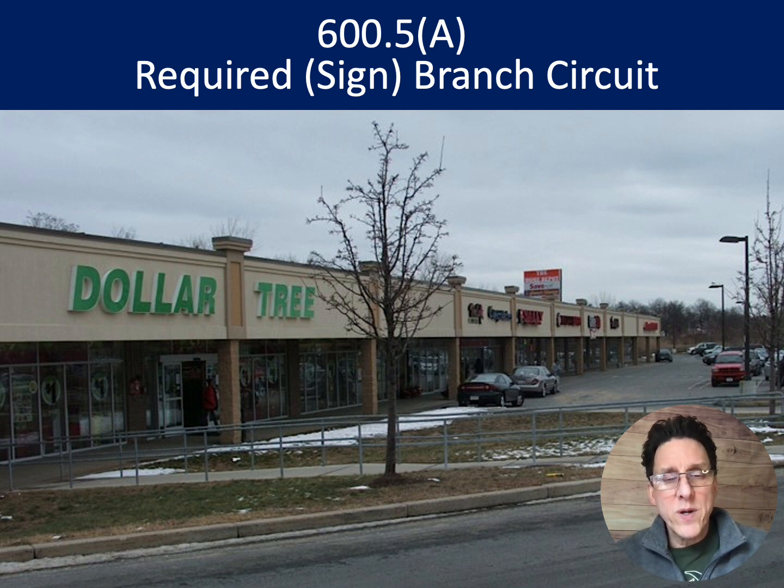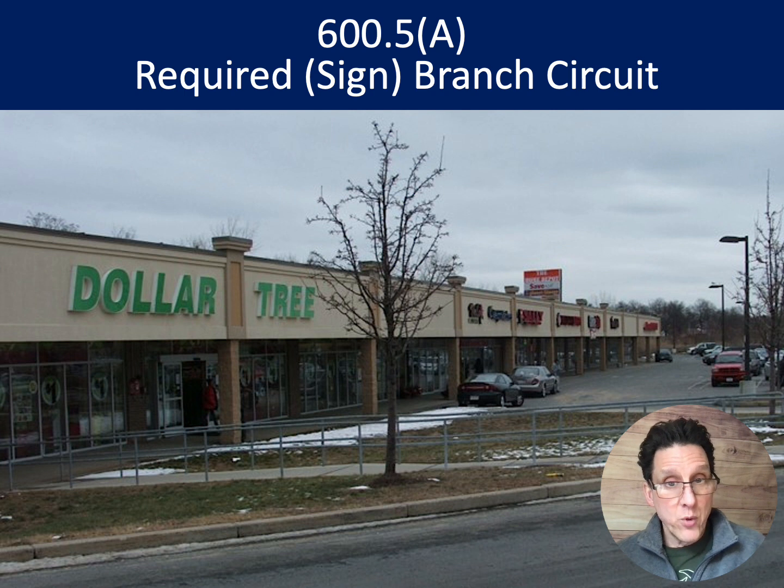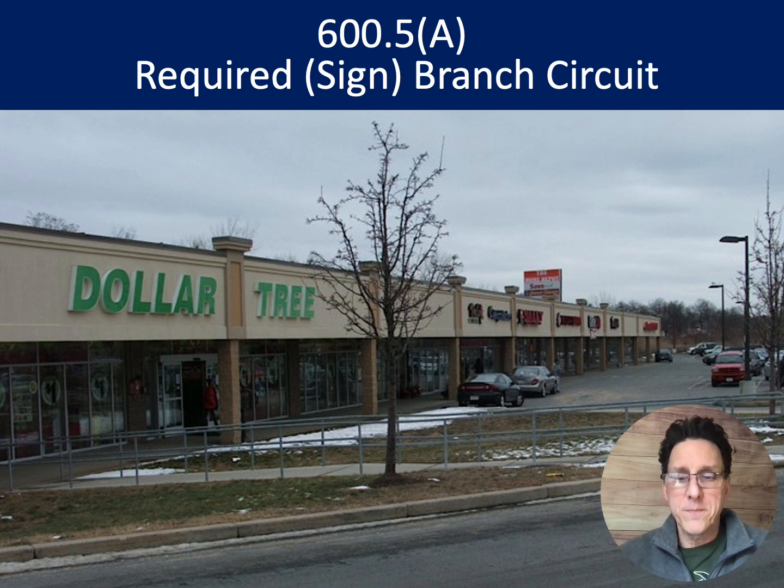And so at each one of these entrances to each store or each commercial space, there has to be a branch circuit supplying an outlet for the sign or an outline lighting system. All right, we need to know some definitions too, like what is a sign and what is an outline lighting system.